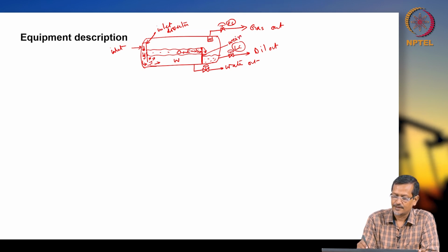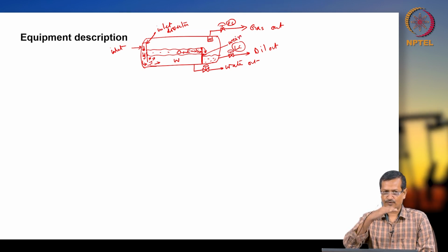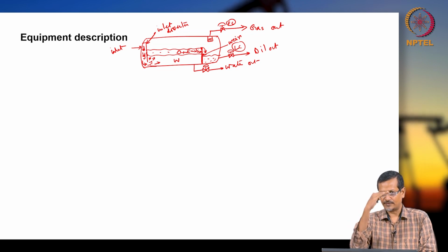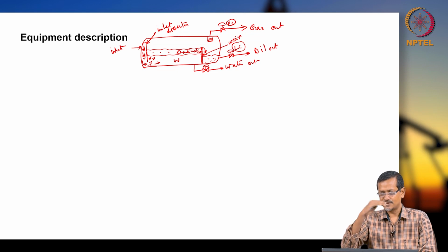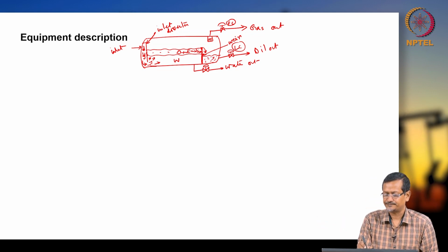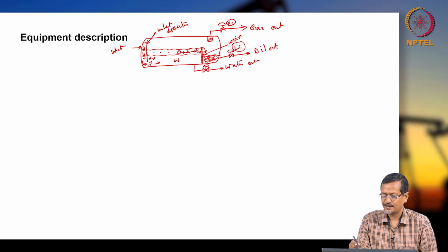Okay, weir. So it is restricting flow. When something is overflowing, it will allow overflow, but it will not when the oil level is lower, so it will not allow water to flow to this bucket or this area. Okay, so whenever this area is filled, you are getting oil out.